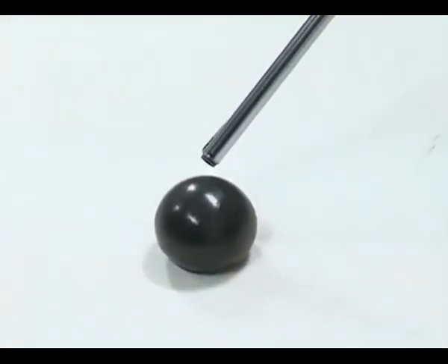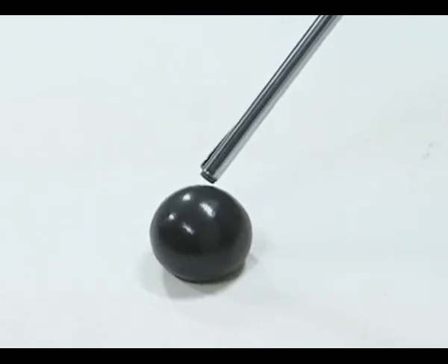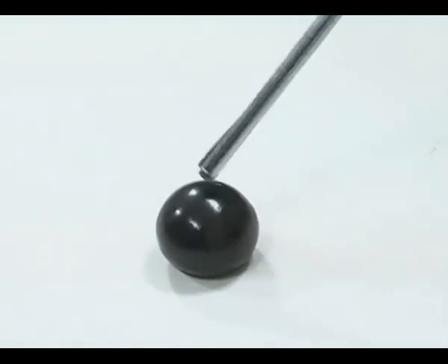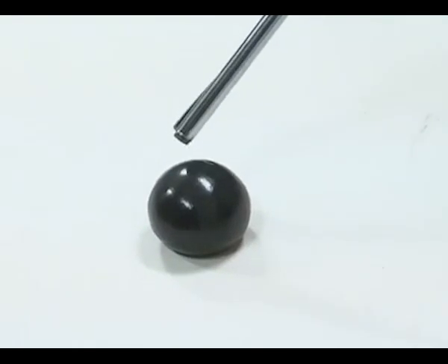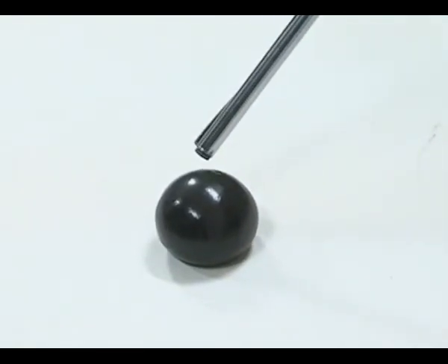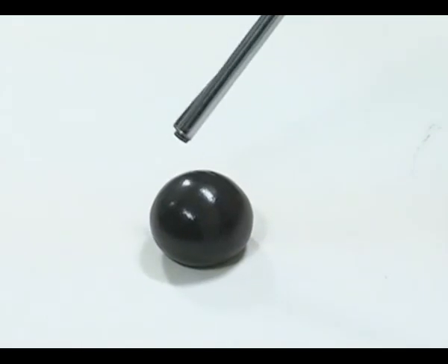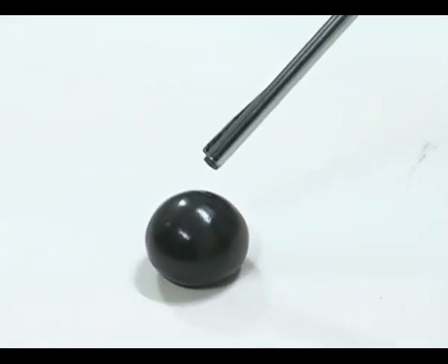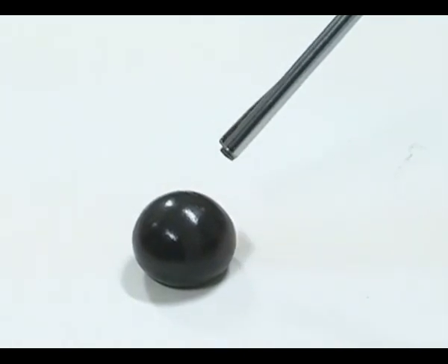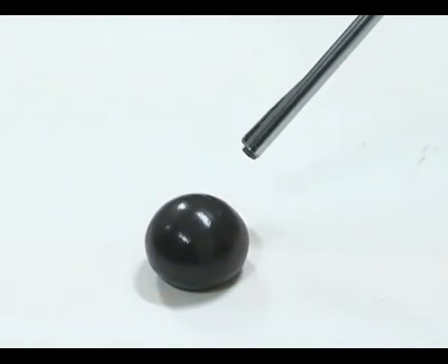Third major element in abrasive flow finishing process is polymer rheological abrasive medium. This is the polymer rheological abrasive medium, and we have placed a spherical ball on the surface. It has three major properties, that is self-deformability, better flowability, and better abrasibility. You can see if we place a spherical ball on a flat surface, after some time it deforms itself into a flat surface.